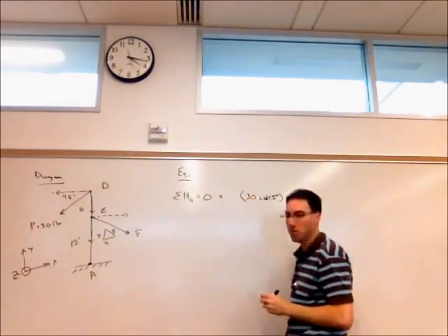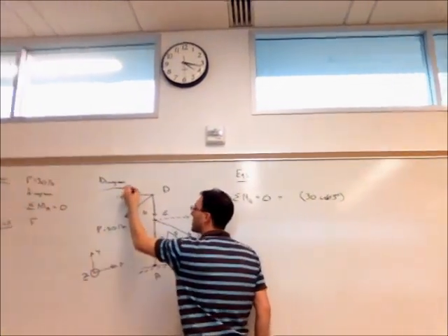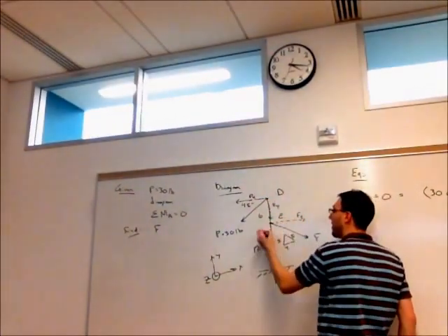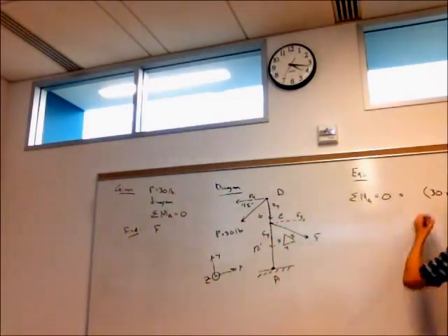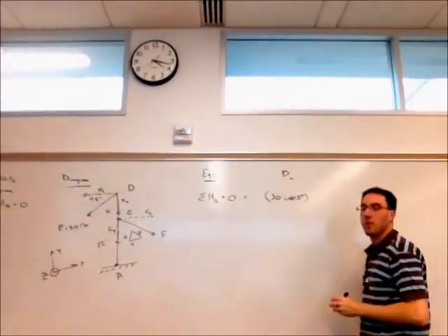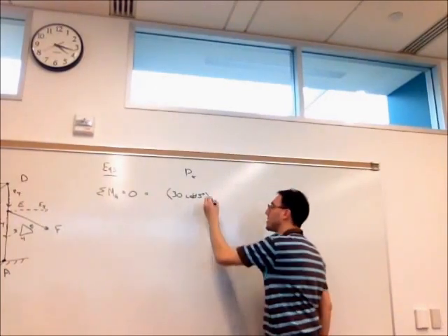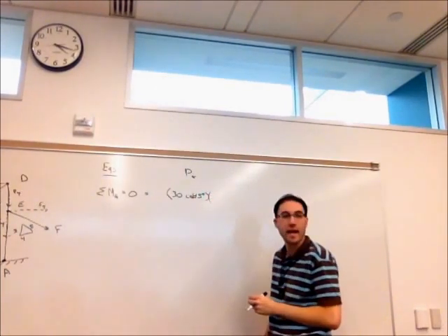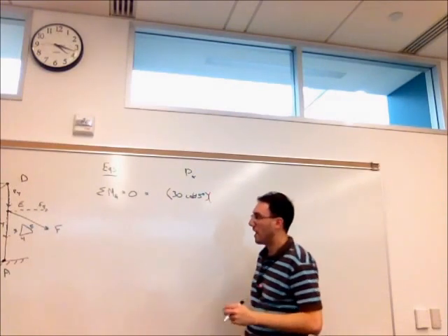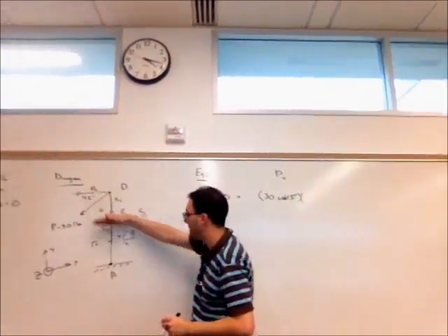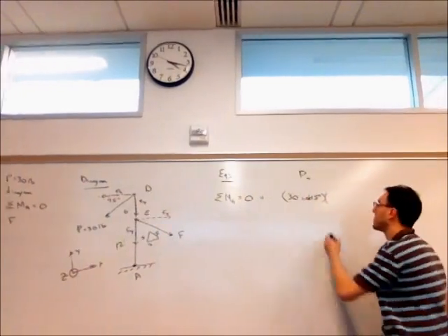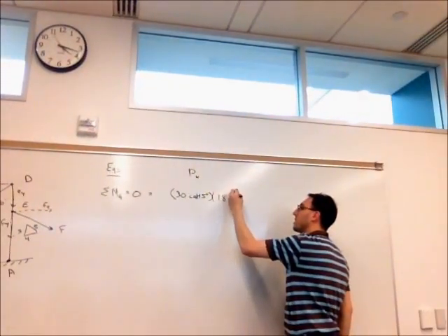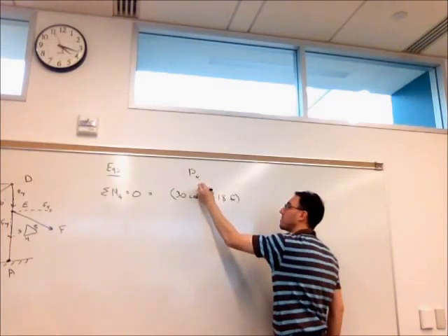Right, so that's the force. I'll call this Px and Py, and I'll call this Fx, Fy. So remember, a moment is a force times a distance. So what is the perpendicular distance between Px and A? Right, so it's 12 plus 6, so that is 18 from A. This is in feet. And this was in pounds.